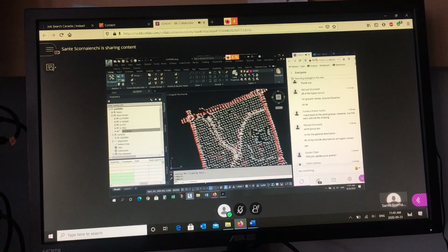Okay, so at the command, save the drawing. At the command line, type in audit, A-U-D-I-T, audit. Hit enter, and then you'll get asked the dumbest question you've ever seen. If we find any errors, do you want to fix them? The default is no. Change that to yes. Put in a Y and enter. And then let it do its thing.